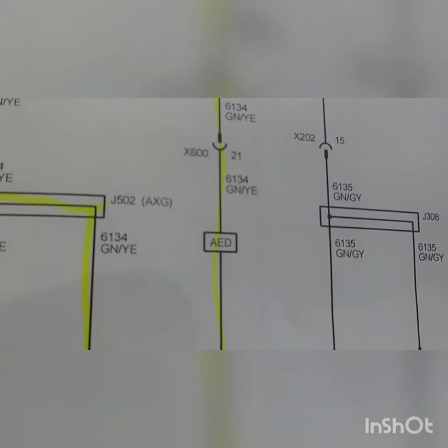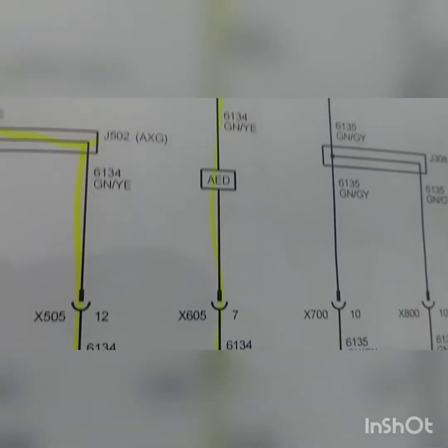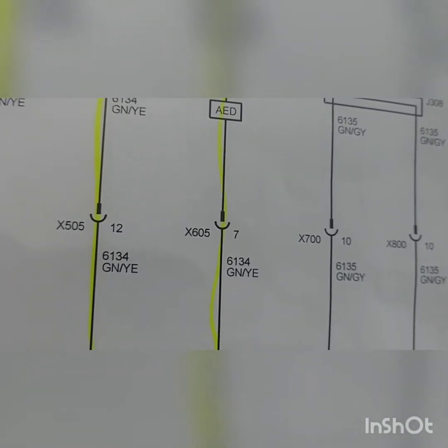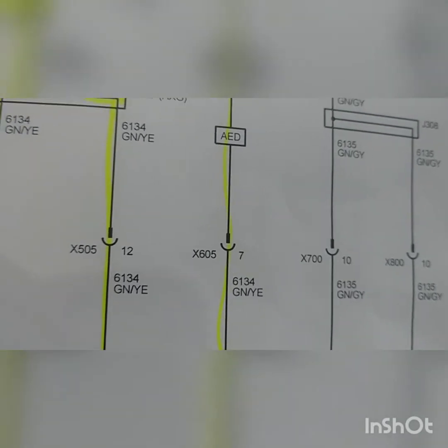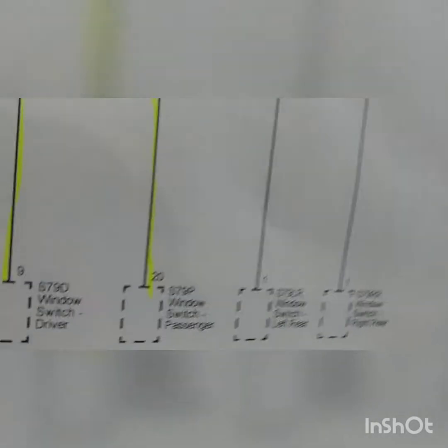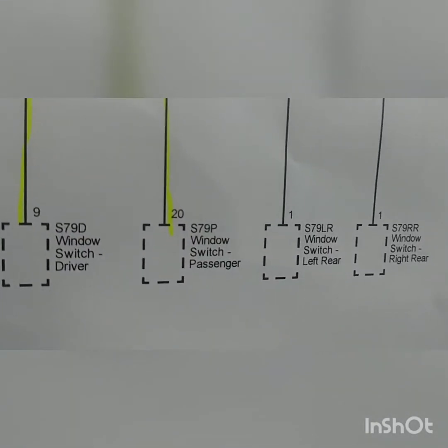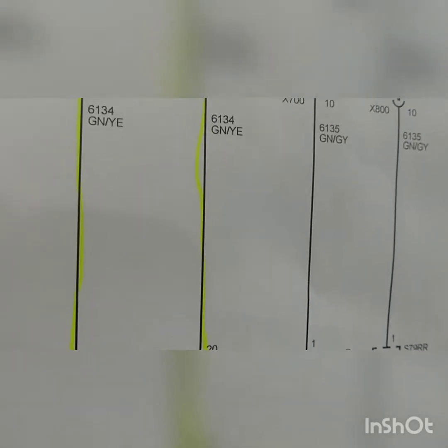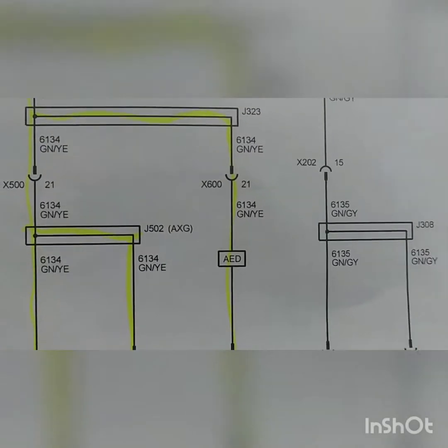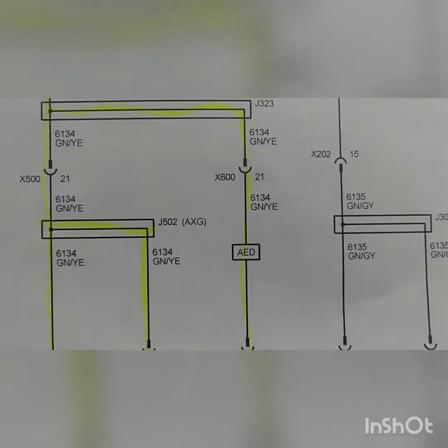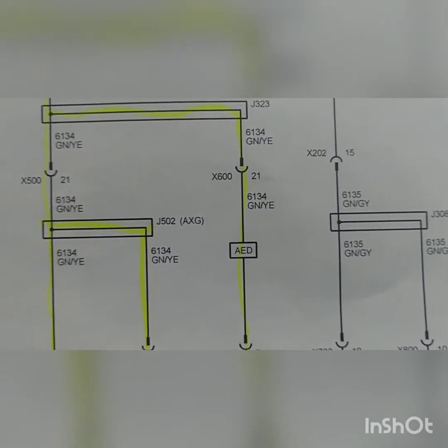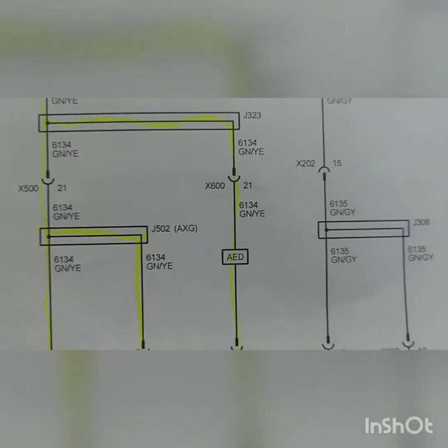It's either the connector at 600, connector 605, which is the connector along the way behind the door panel, and or it could be a short to ground internally to the passenger window switch. All right, so let's reconnect our connector 600 back. We're back at 0 volts now. Remember, we're back probing pin 10 on connector K9 on the body control module on the harness side.